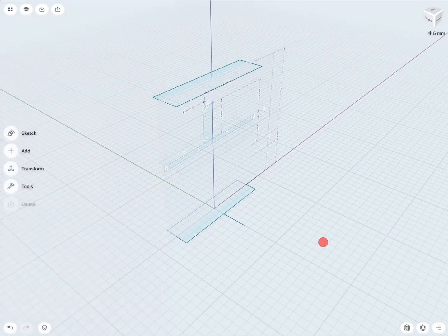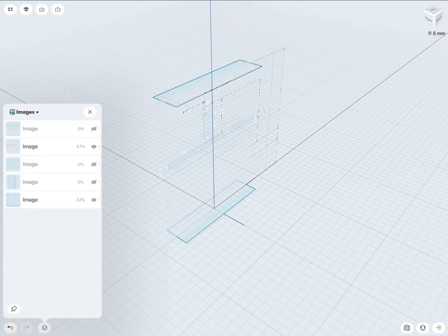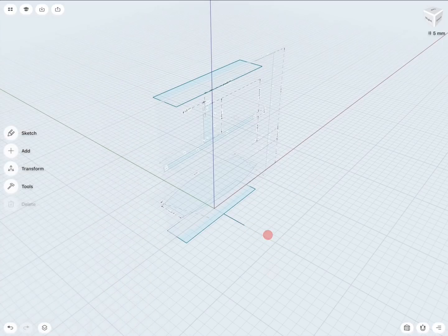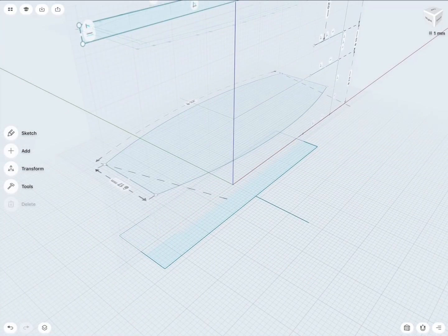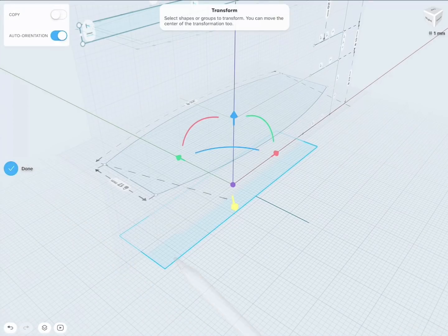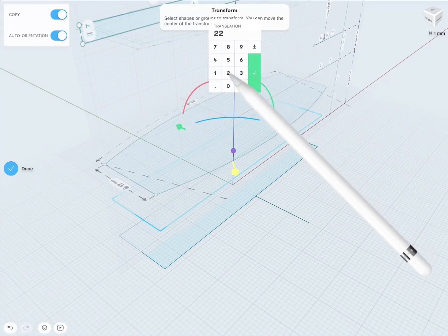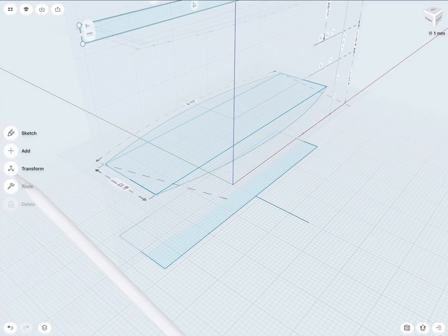Actually, that's not the one I wanted. Give me 1 second, that's the incorrect one. Oh, there it is, okay. So I have to now create this sketch where this is spelled out. Also here again, I could go to the Move command, select my sketch, this is 22 millimeters up. So I bring this one up, 22 via the Move command, done. Very nice.